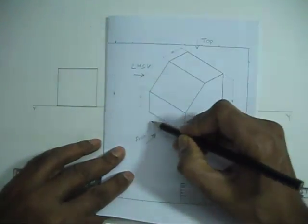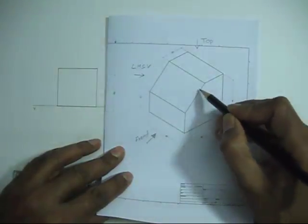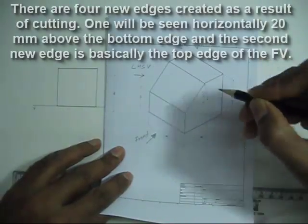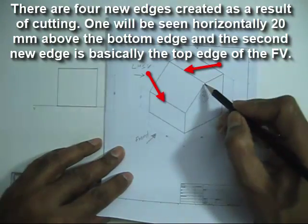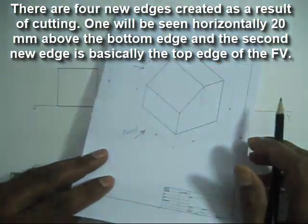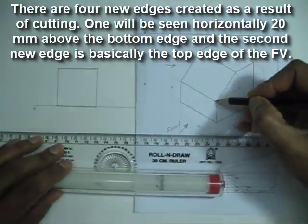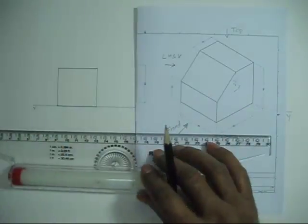So in the front view, we will see this part. The inclined part will be projected in the front view. So we will not see the true dimension of the inclined part, but rather the projections of it. So there are 4 new edges created as a result of cutting. One will be seen horizontally 20 mm above the bottom edge, and the second new edge is basically the top edge.